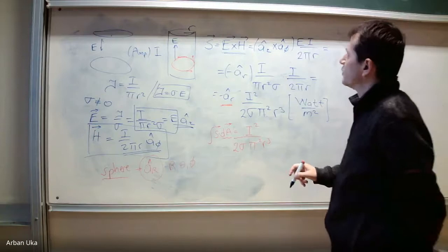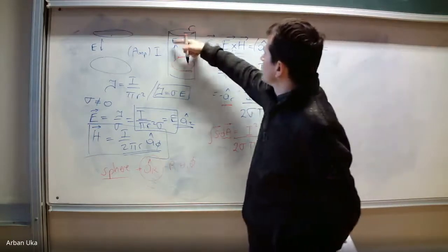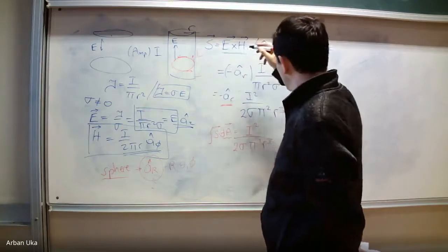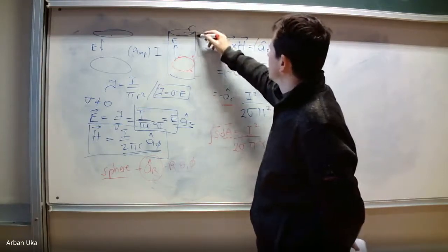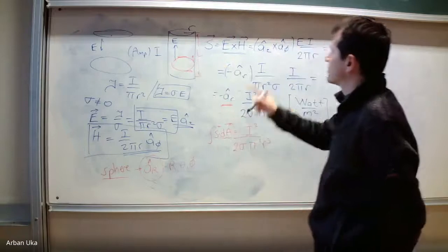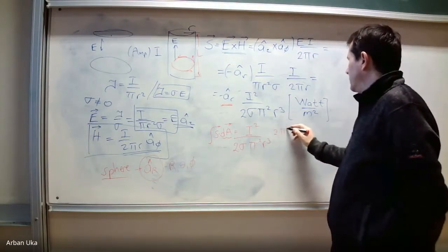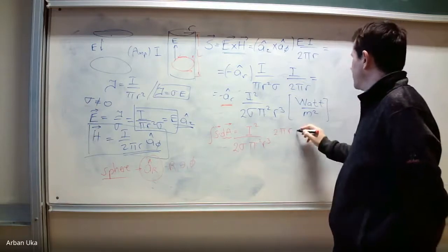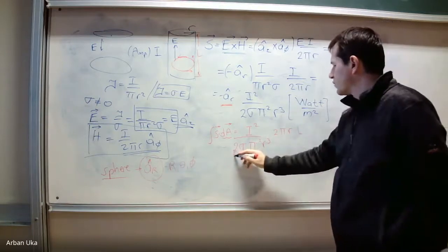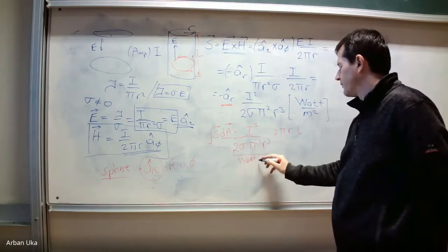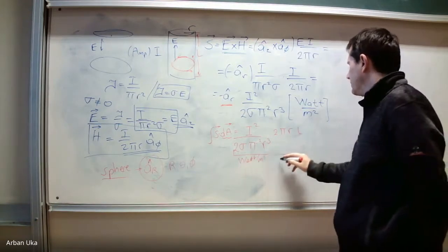So this we multiply with the outer surface area here, and let's assume that the length here is L. We haven't used L yet. L is just the length of this wire, and we do here 2 pi r, okay, times L. So now this was watt per meter square, times meter square.